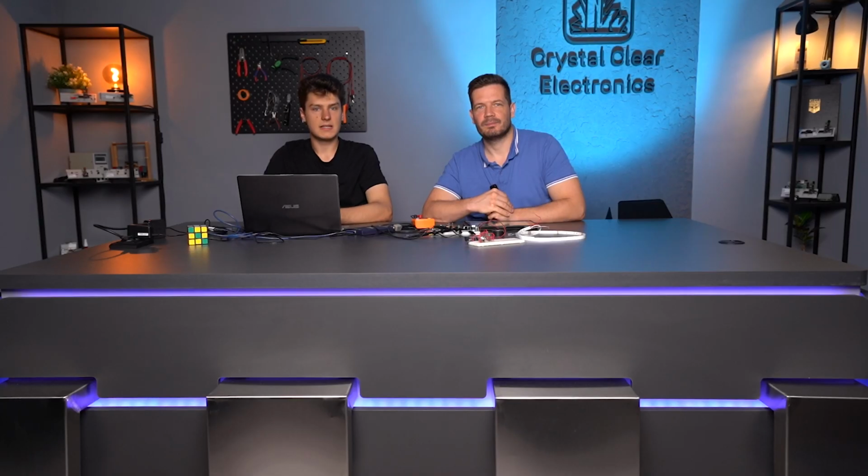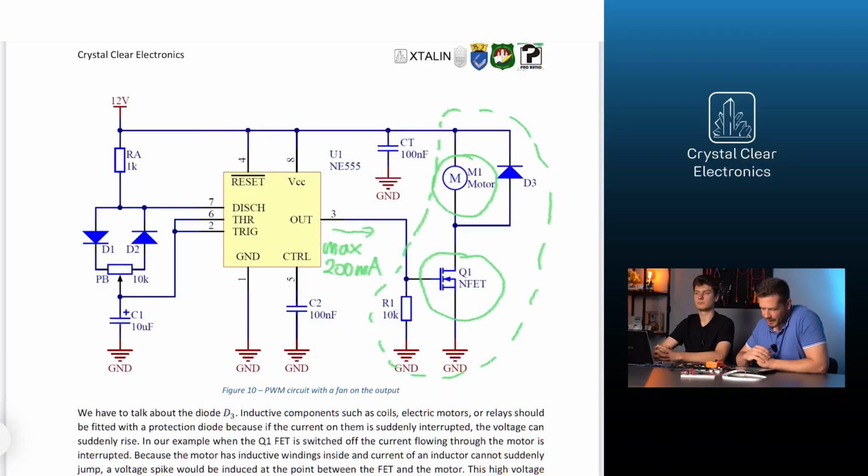You are referring to the 13th chapter on DC engines, right? We heard about self-induction there. So now, self-induction voltage occurs at the motor's contacts from sudden switching? Exactly. And this self-induction voltage can be of the order of kilovolts, so it would destroy the FET.